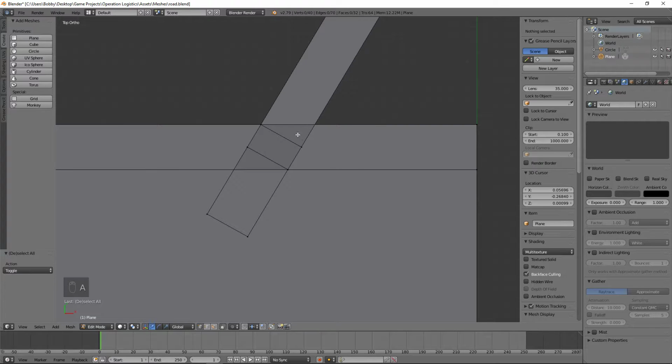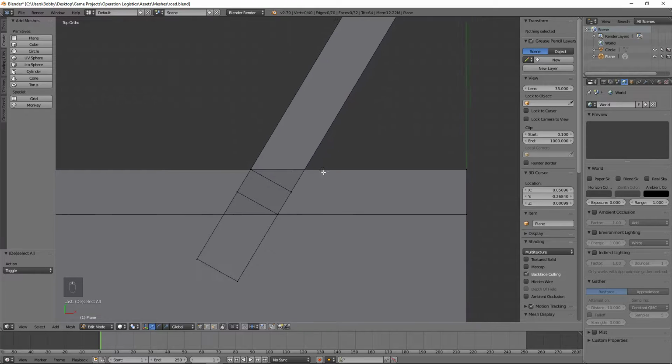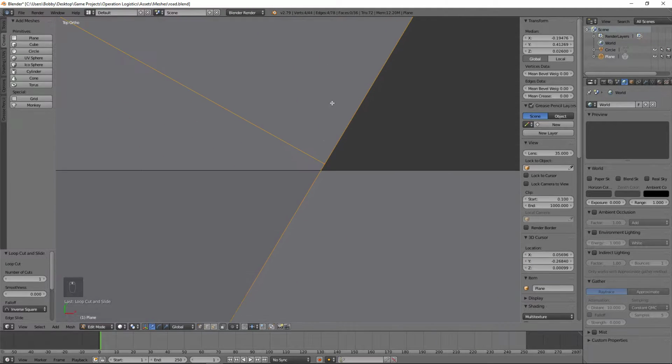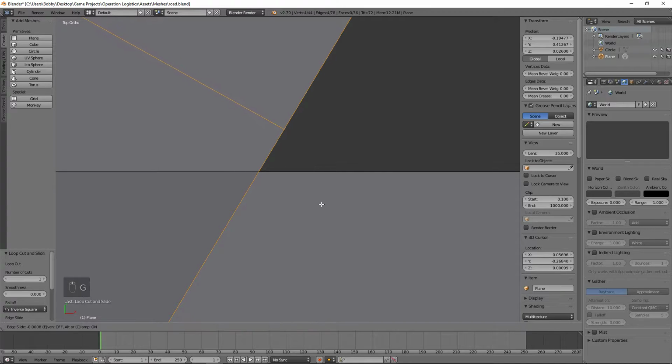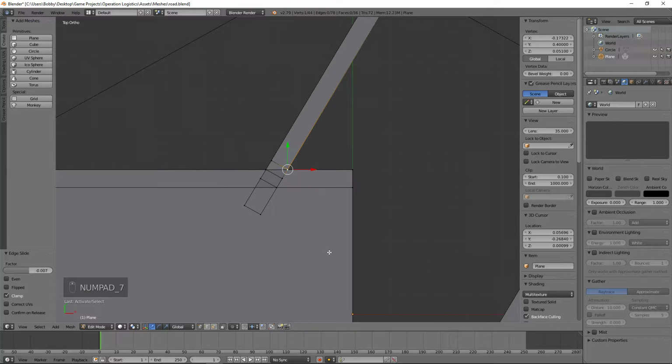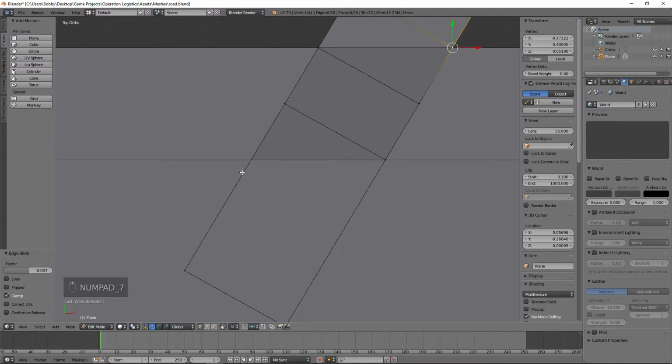And then we'll need the same thing on these two locations. So I'm going to go ahead and do another loop cut. Take it in approximately correct, and then zoom way, way in ortho mode. And place it basically right on. Right about there-ish. And that should be at 0.4, and it is. Perfect. Now we need a vertice here.